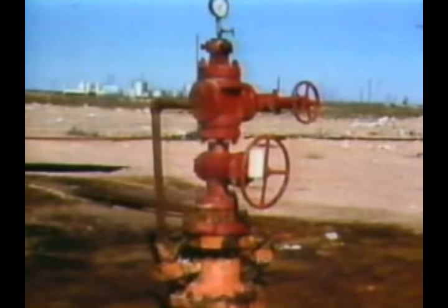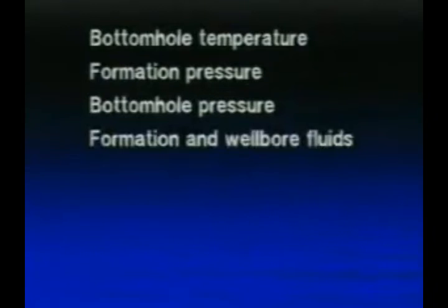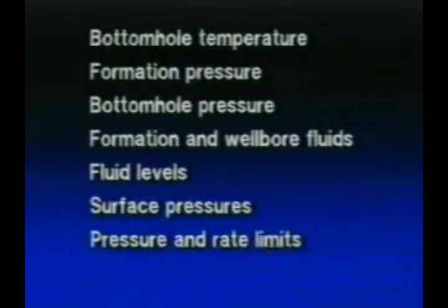Other conditions that must be specified or estimated include expected bottom hole temperature, formation pressure and bottom hole pressure desired, formation and wellbore fluids, fluid levels in tubing or casing, surface pressures, pressure and rate limits for surface facilities, and the need for H2S equipment, if any.